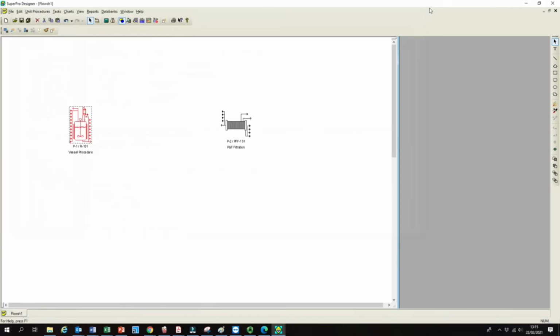So let's close this one. I'm going to add some streams which allow me to load my reactants into the reactor. To add input streams, you have to press this icon. It's called connect mode. Just click it one time and then put it anywhere on the screen. Now you will see something like "add stream" next to your cursor, which means this function is active. Just click somewhere on the left side of your reactor and then connect it with any of these ports. So what we created now is a new stream.